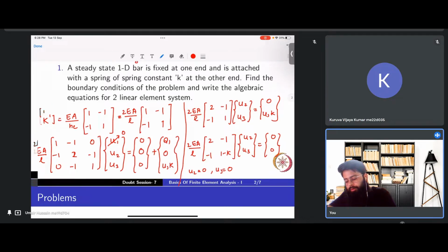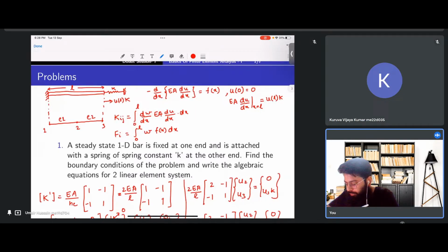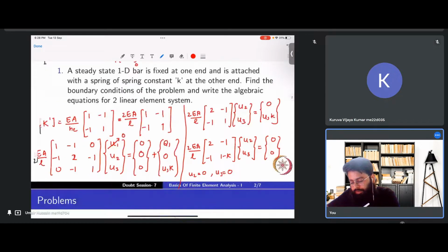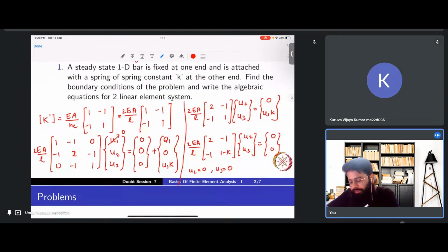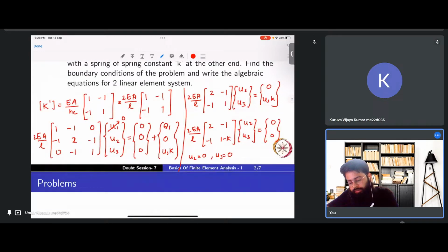So if you see the problem, we don't have any forces involved. It's just a simple bar kept at its place. So until and unless it is being held by any force, maybe any body force or some point force, there won't be any movement within the bar, and there won't be any deformation. Every point would stay wherever it is. So you'll get the deformation at every point equals 0. So essentially our solution Ux would be 0. This is the solution for the problem.